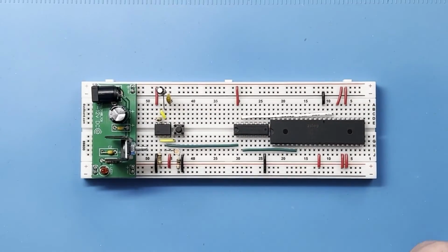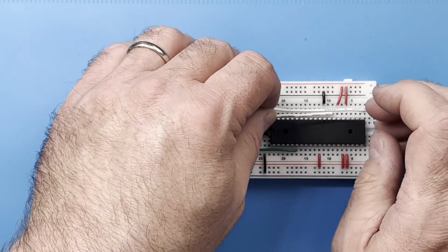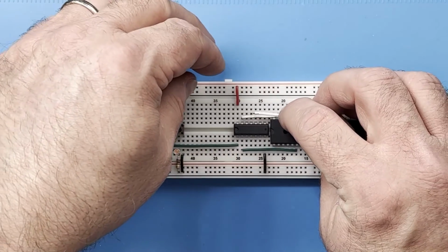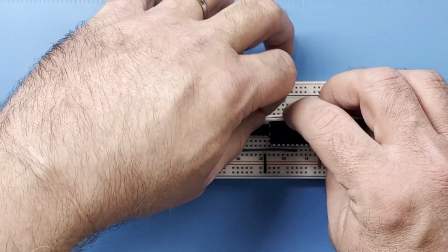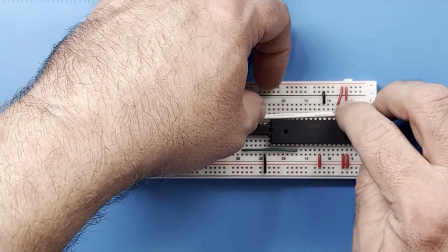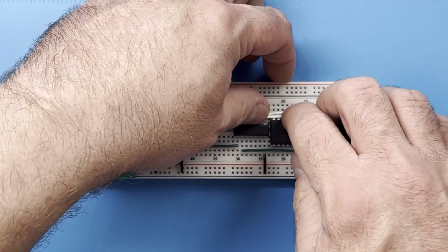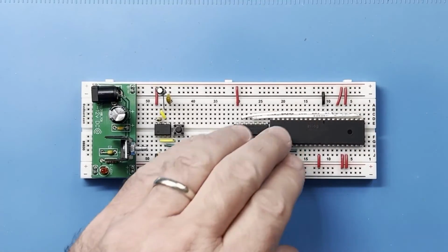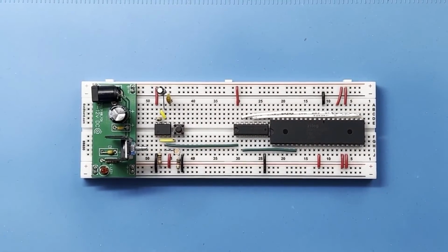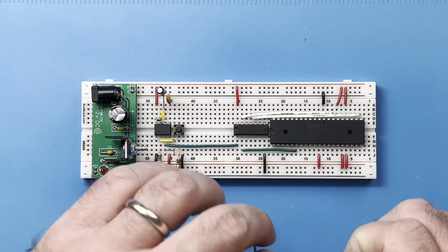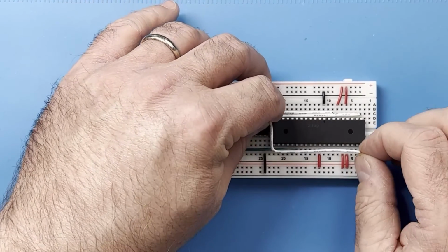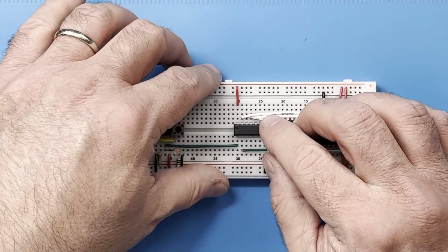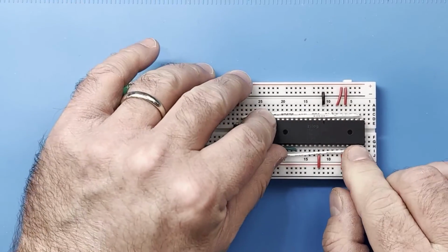And then the read pin, which is pin 21, to the second input on this same side here. And get that in there. I'll throw it down here just so that it fits better. And then the MEMREQ pin, which is pin 19, I want to put that to the third pin over here, which would be pin 9. So I'll stick that right in there and hook it up to 19. There we go. All right.